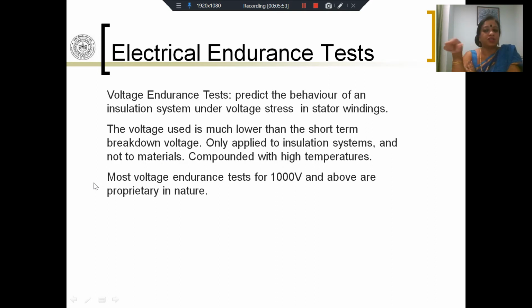If you remember the voltage time characteristics related to a dielectric material, when you apply elevated voltages, breakdown is very short, but much lower voltages can cause breakdown over a long period of time. And with aging test, that is the kind of levels we are interested in. We are not thinking of transient over voltages, but we are talking about maybe constant voltages, which are not even over voltages, but maybe very much the normal voltage, or maybe slightly above the normal voltage. Under normal circumstances, at short time, we probably do not expect any kind of failure to happen.